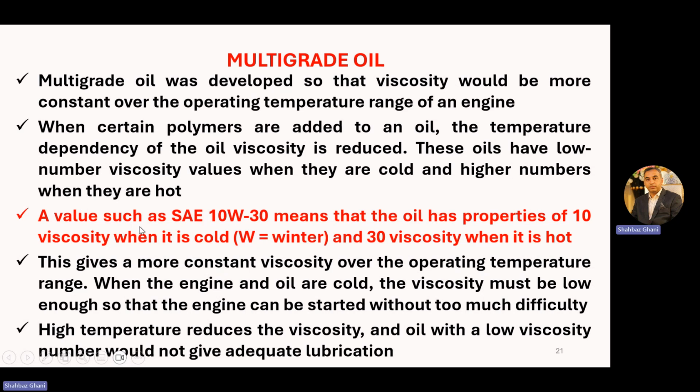It is written as a value such as SAE 10W30. SAE 10W30 means that the oil has a viscosity of 10 when it is cold, W stands for winter, and 30 viscosity when it is hot. This gives a more constant viscosity over the operating temperature range.